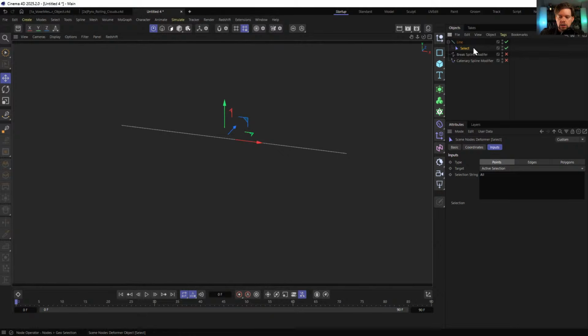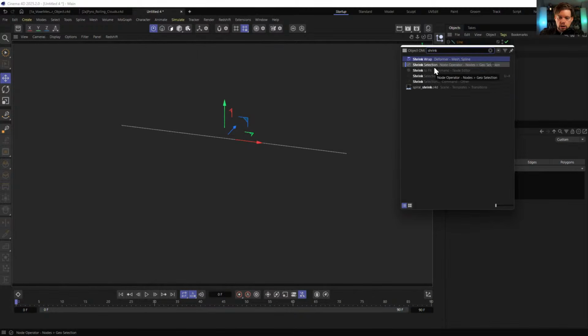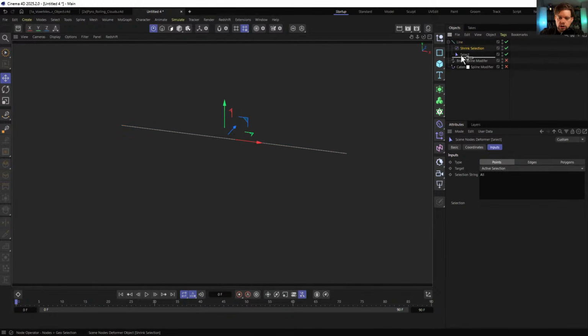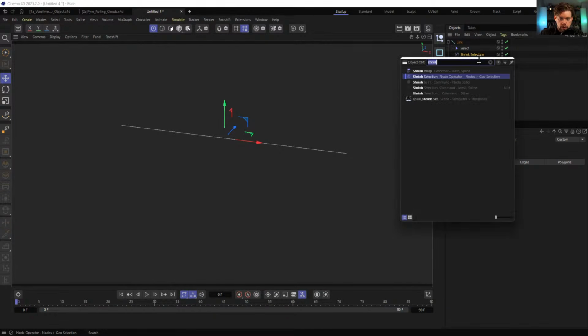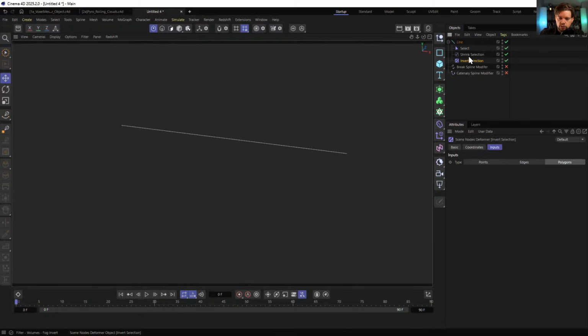So first step, select all of the points. Next step, shrink my selection. So there's a shrink selection. I don't know if this works on a spline. Shrink selection, points. So it's going to shrink by 1 step. And now I'm going to say invert, and we've got our invert selection right there. So let's invert after we've done that. So in theory, I've now selected these outer points. Unfortunately, there's no way of seeing it in the viewport, that what we've done.